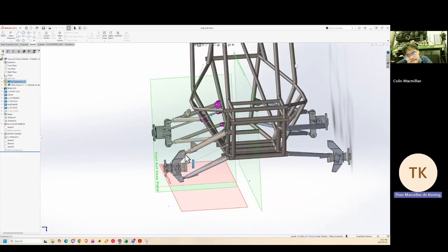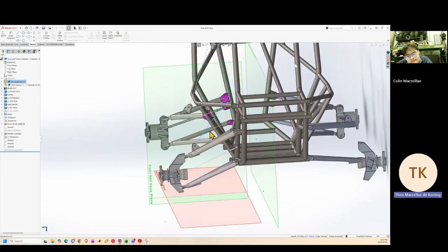As the control arm pivots up, the angle between the shock and the control arm gets smaller over time. So more of the reaction force of the shock turns into axial loading versus bending on the control arm.